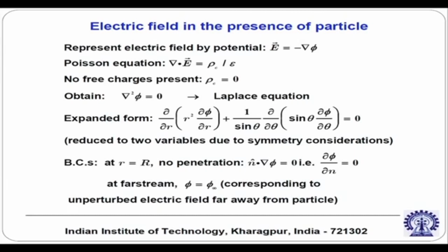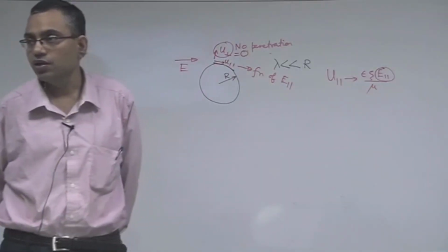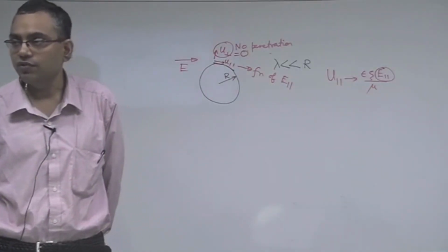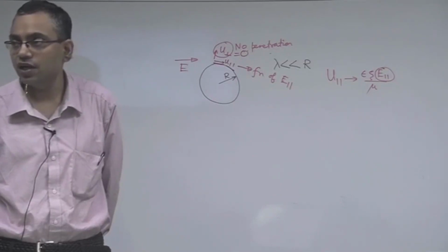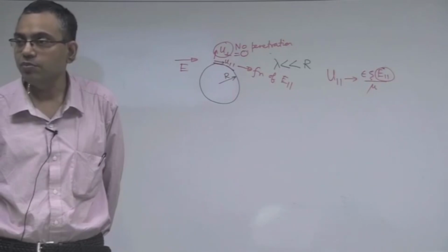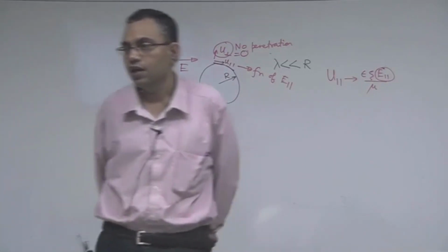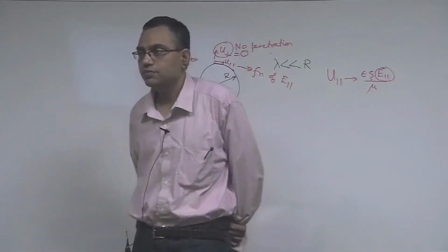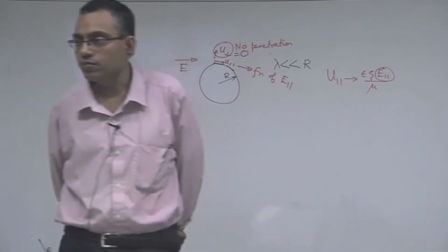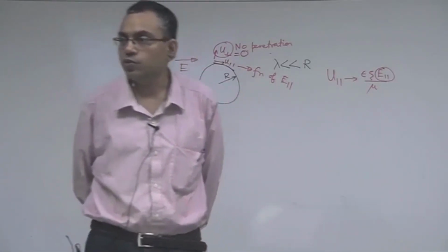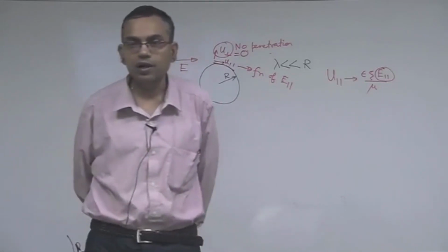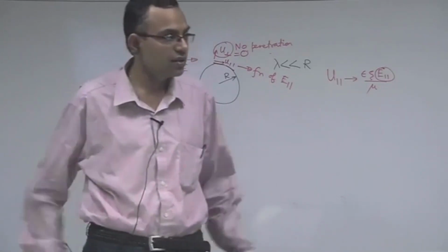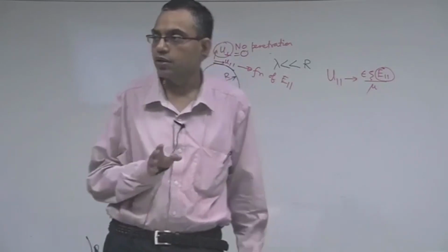Here we are interested to solve for the applied field, because if you recall the derivation of the electroosmotic velocity, the result was minus epsilon zeta E external by mu, when we considered the electrical body force and the body force due to the osmotic pressure. I am just trying to recapitulate because the fundamentals are important.